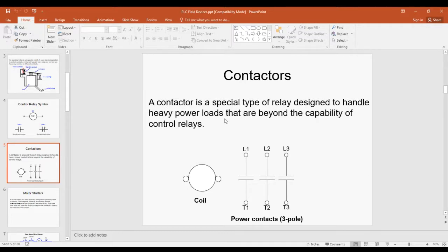They have a 240 volt. You know, AC in the house is usually 120, but you can have a machine like a dryer that's 240. Well, it turns out that you can have a single phase AC voltage or current, which is when you plug something into a wall outlet, that's mainly what you have. Single phase 120 volts, one sine wave. You can have a two phase 240 volts, or in this case, I'm showing you this contactor with three contacts.